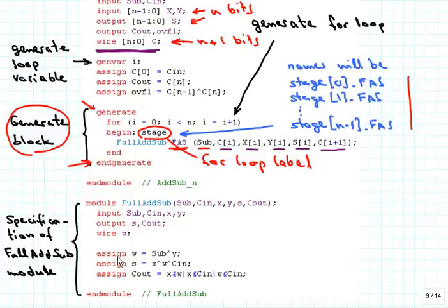So here the W is the ones complement of Y, for the case when we are using this as a subtractor. Then we have the sum, or the XOR actually, which creates a sum bit of X, W, that ones complement, and carry input. And the carry output is computed as the majority decision on X and W, or X and Cin, or W and Cin.